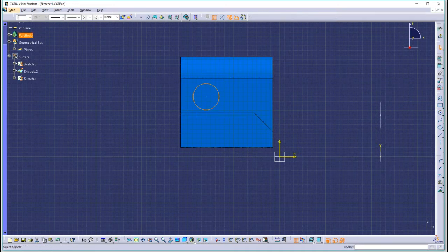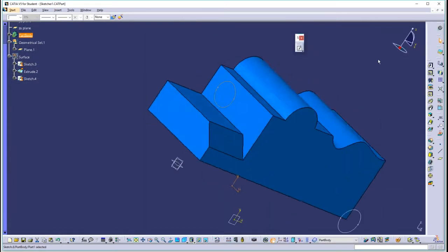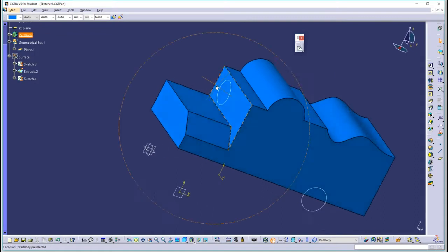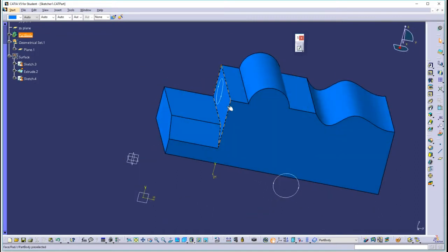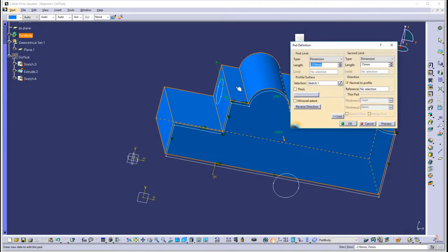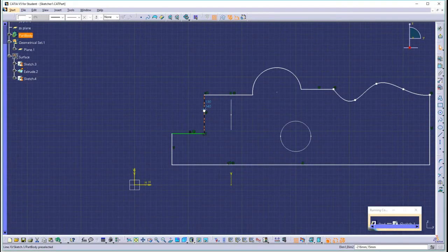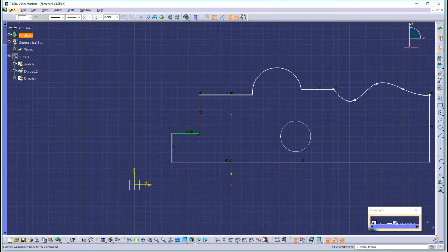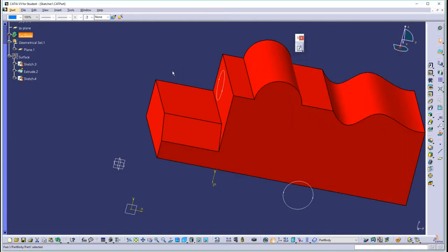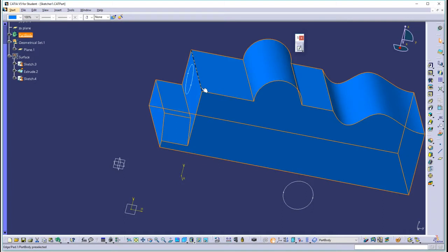So here we'll draw a little circle. We'll exit Sketcher, and now that sketch is on this face. Now, if I were to change that face, let's double-click this pad and go into the sketch for this pad. So that's this face right here. If I move this out this way and exit Sketcher and say OK, and then hit Update, that face moved out, and of course that is the support for the sketch, so the sketch moved with it.